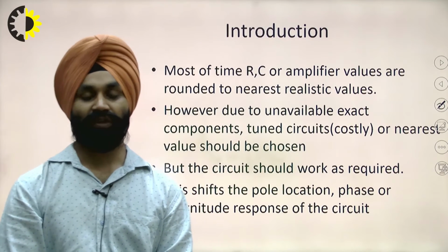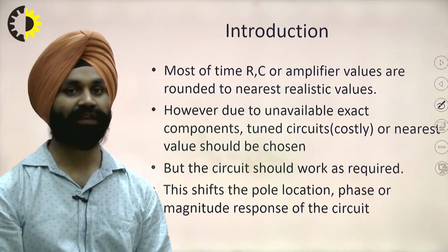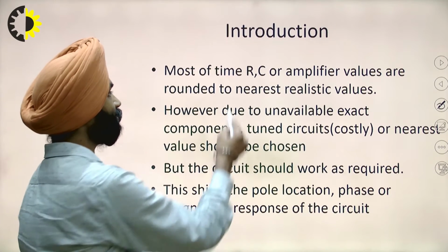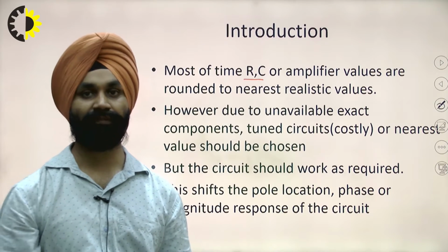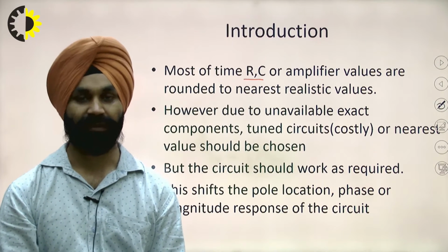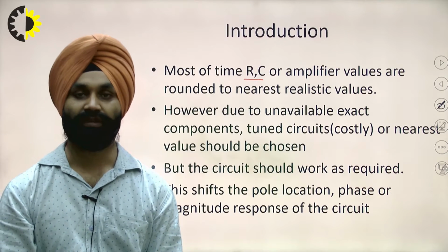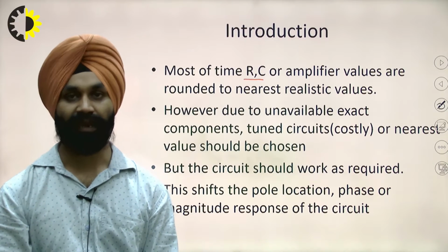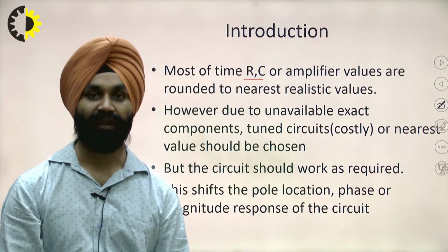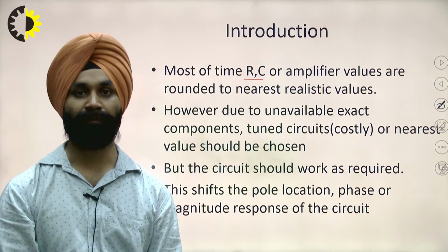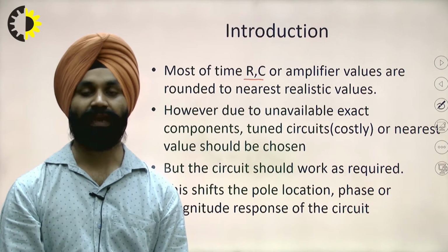Most of the time when we design a filter, we need RLC, and we have replaced the value of L with some other type of circuits that we will see later, like GIC and gyrators. So we are taking R components, C components, and the amplifier values, generally op-amp or transconductance. So we take its appropriate value.